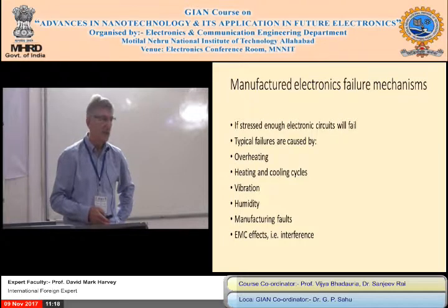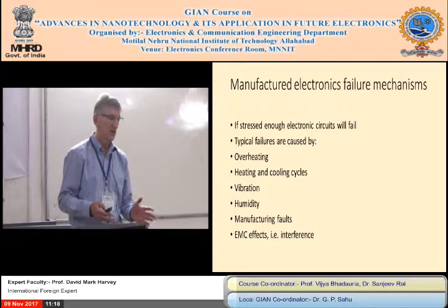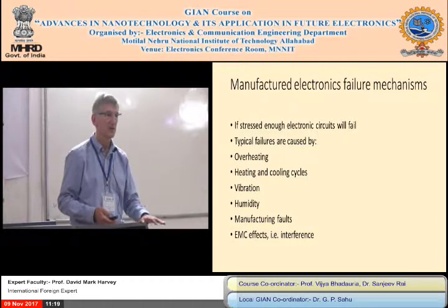So when you get a failure in a manufactured circuit board, the weakest link normally is the solder joint. Okay, and solder joint materials are changing. We used to have leaded solder. Lead came out of solder, or it's supposed to be out for most cases, because it's dangerous to the environment. You have lead-free solder. Also in solder, we put in things like nanoparticles to change the way the solder behaves.